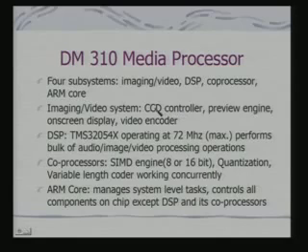Now the CCD controller, if you compare this with your OMAP interface with the device, OMAP was providing a simple serial or parallel data interface. Here you are talking about a CCD controller, that means you can actually control the sensor itself. So that sensor control logic now goes into the SOC. In the case of OMAP, it is expected that your camera is providing the data and you have the interface to get the data. Here, how to extract the data from the CCD sensor itself and how to manage the CCD sensor, that hardware becomes part of the SOC.